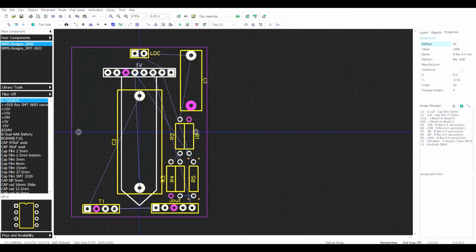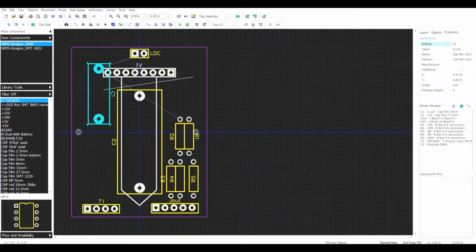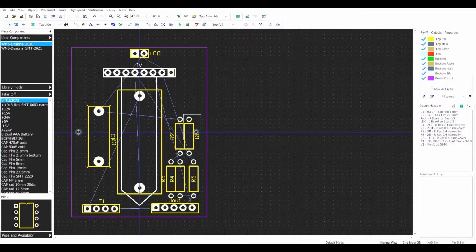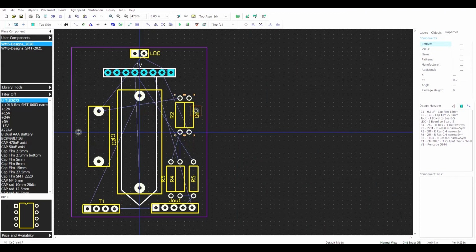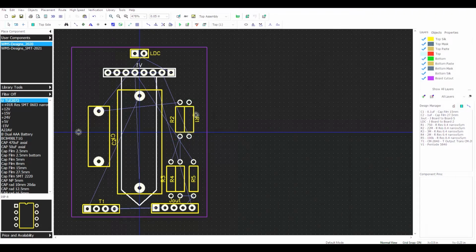The issue here is that, actually I'm just going to pull this capacitor over to this side. I think that'll make more sense. And then I'll move these up. I just want some room between the resistors so I have a place to put the markings, the ID numbers. That should be good. Go back into F10. Actually, go out of F10. I want to put this one back. I want them all to sit next to each other the way I want. I like my circuit boards to look a certain way.